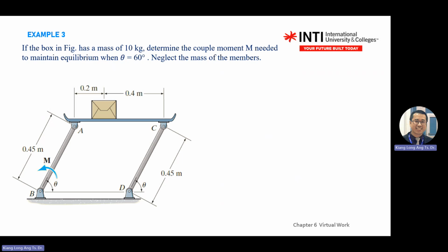So change the whole system into A point, B point, it depends. But you know that there's a support here, so there's a pin here. It cannot move left, right, up, down. So there are two forces in D, and two forces in B, Bx, By. Then what happens to this object if you let go from rest? How will it behave? It will rotate left or right.